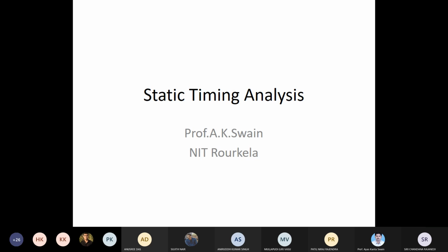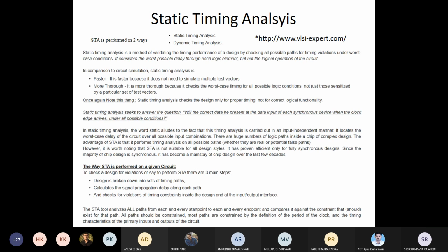And we also know 60 to 70% of designs in a system are digital design. So that's why we call it RTL level design, register transfer level design. So registers are there, and when registers are there, clock is there, so flip-flops will be created. Between two flip-flops, we have to verify whether it is maintaining the timing properly or not. So you just assume that your entire design is divided